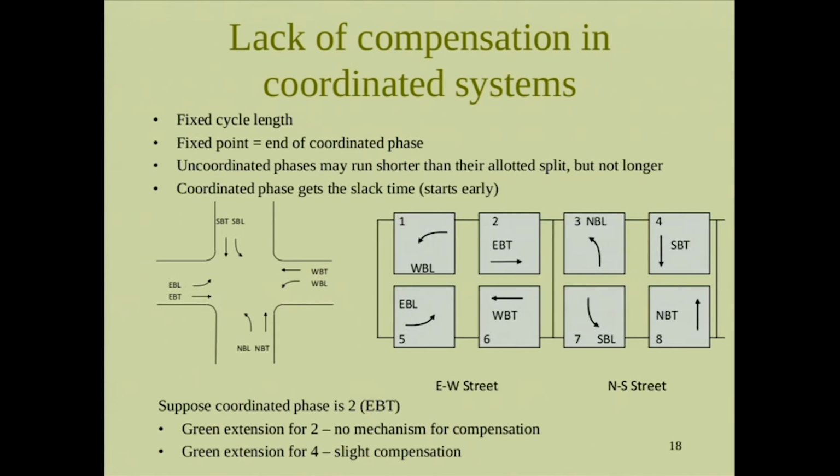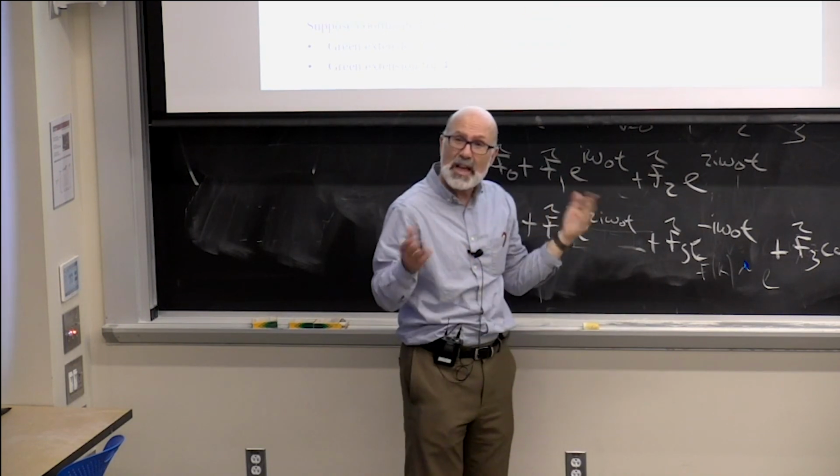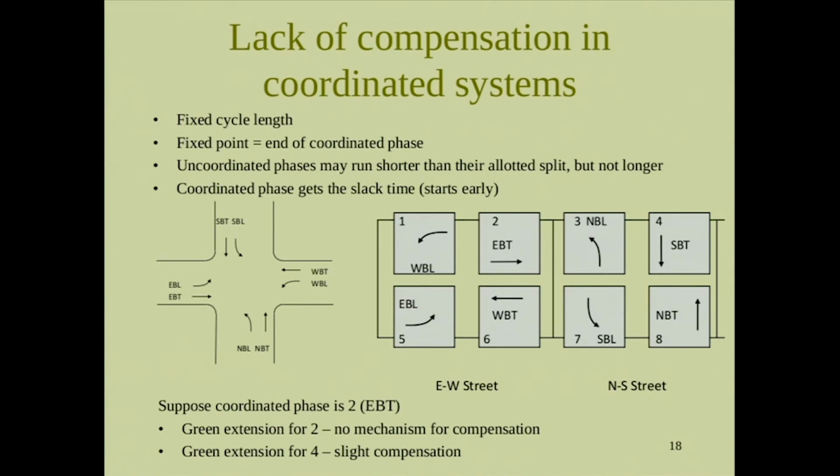There's an upper ring and a lower ring, and the rings that are in parallel can move together. So when the light starts green, eastbound left and westbound left, 1 and 5, they're green together. What comes next, 2 or 6? That depends. Whichever one has more traffic, 1 or 5, will stay green because it has detectors, while the other one gaps out. So maybe 5 gaps out first because it had less traffic.